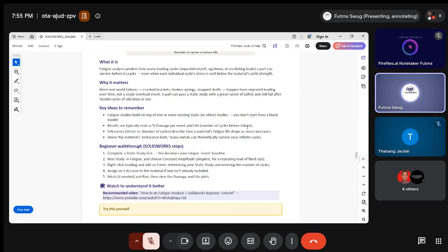This part can withstand it for this amount of cycles. And then if you can withstand it for this amount of cycles, you can actually interpolate it to know, okay, for 5 years or for each year, this is the particular work cycle that this product can go. And then you can calculate if this product will last or not.